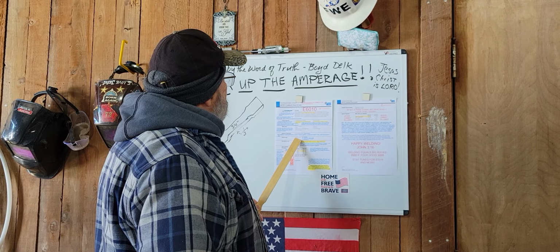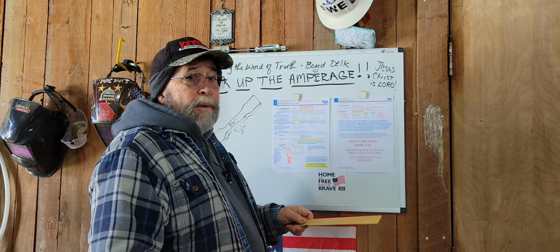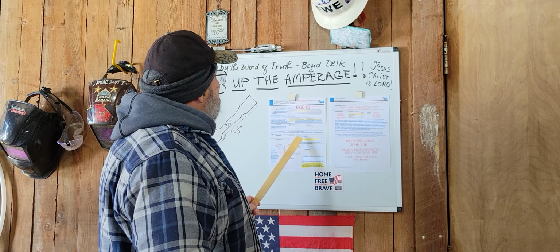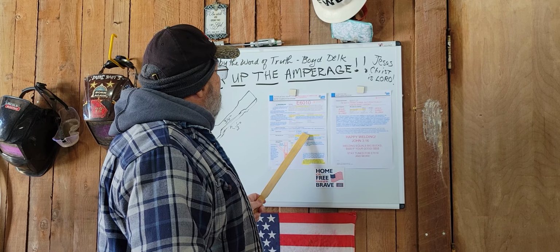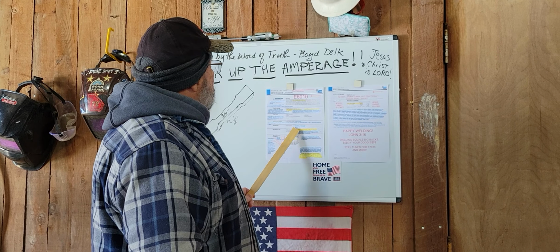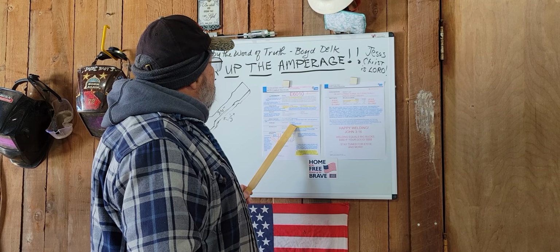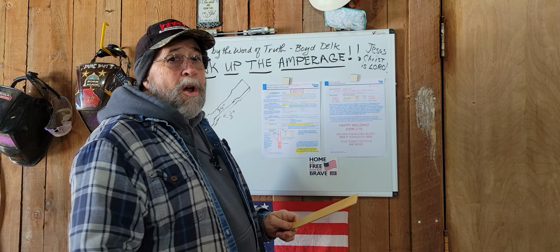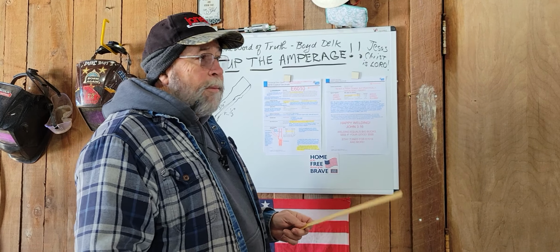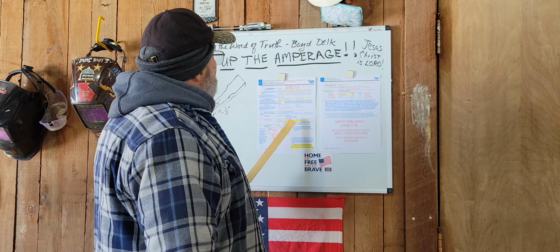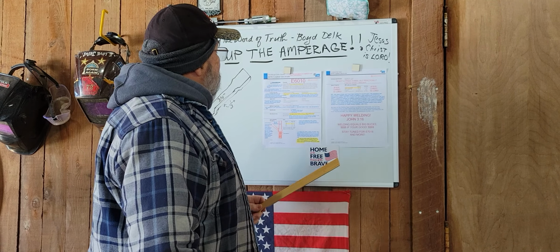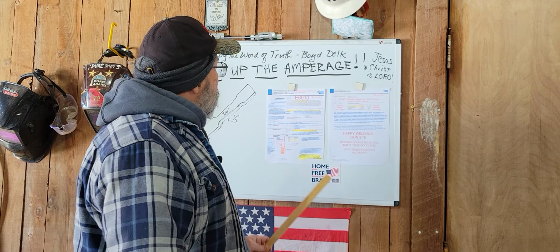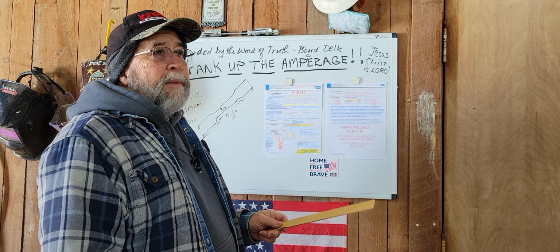Now, just to break down the E6010 electrode: E equals electrode, 60 equals 60,000 pounds tensile strength. The 1 in E6010 means it can be used in all positions, overhead, flat, doesn't matter. And the 0, as in 10, is the flux makeup.